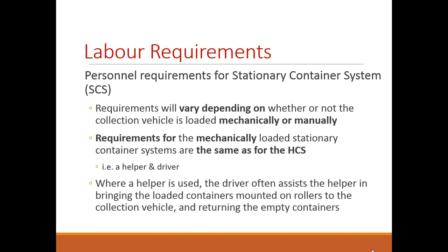So the requirements for the mechanically loaded stationary container systems are the same as the HCS. Remember, we just looked at the hauled container system, and that would be a helper and a driver. Where a helper is used, the driver often assists the helper in bringing the loaded containers, which would usually be mounted on rollers. Remember, this is a mechanical collection system. So loaded containers which are mounted on rollers would be taken to the vehicle, attached, emptied, and then they will return the empty containers.